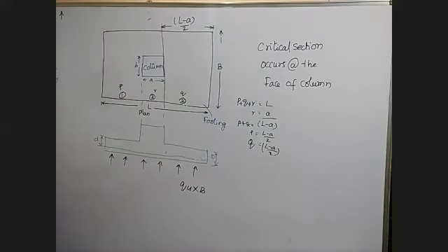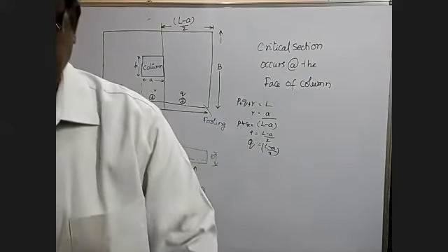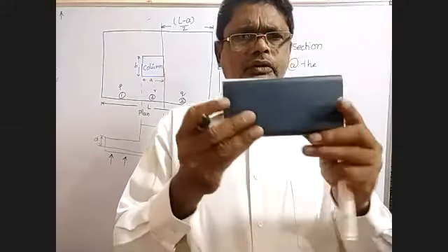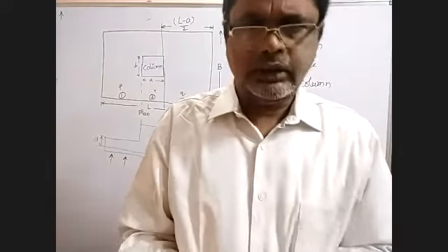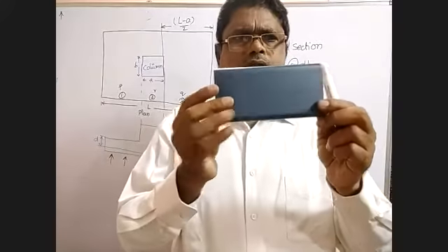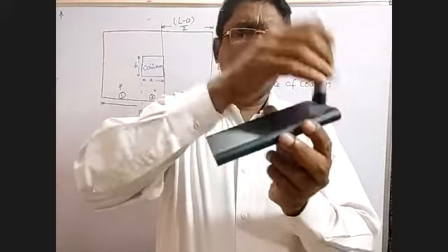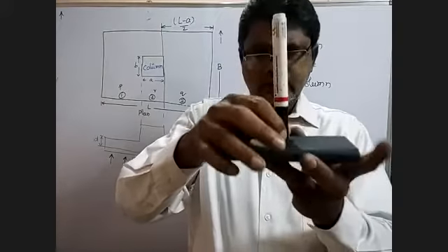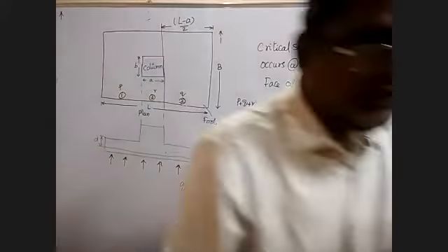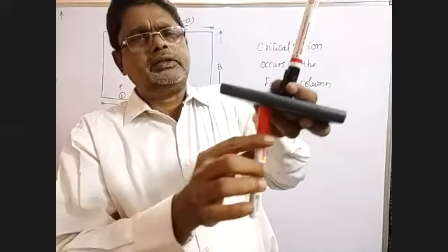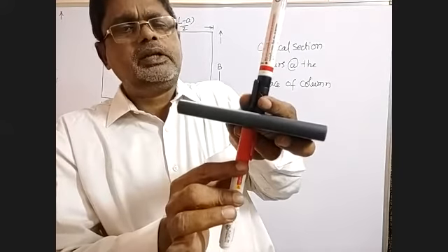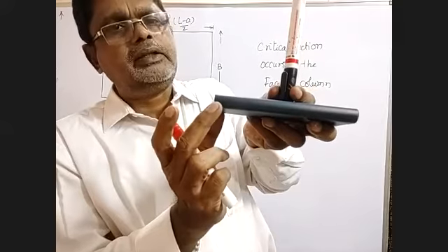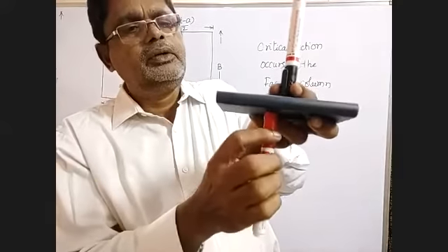Okay, now see here, the pressure here is acting under this plate. This is the footing, this is a rectangular footing. Now here you have a column exactly at this edge of this footing. From the bottom, soil pressure acts over this B length, QU into this B length.